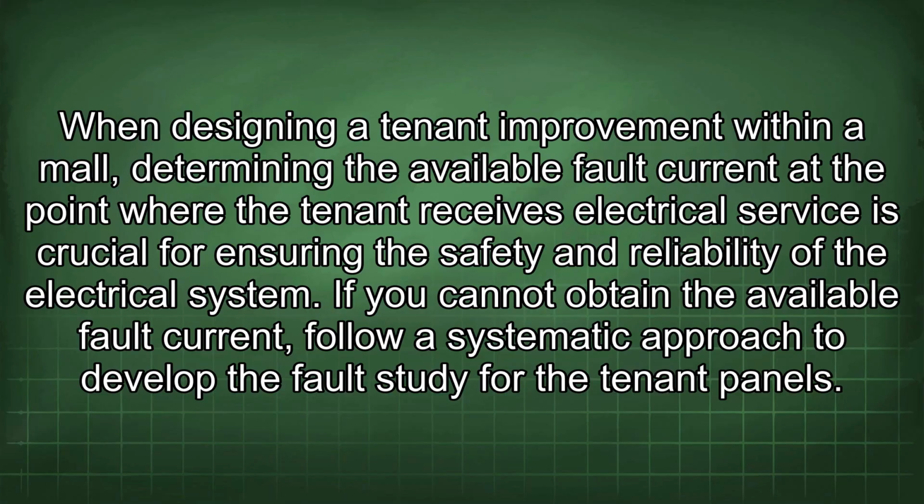When designing a tenant improvement within a mall, determining the available fault current to the point where the tenant receives electrical service is crucial for ensuring the safety and reliability of the electrical system. If you cannot obtain the available fault current, follow a systematic approach to develop the fault study for the tenant